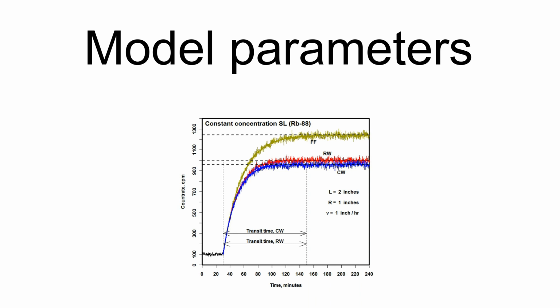Line loss refers to the losses of particulate matter in transit from a sampling point to the monitor, thus the concentration measured would be somewhat lower than that in the original sampled air. This factor is meant to compensate for these losses. Sampling lines are specifically designed to minimize these losses, for example, by making bends gradual as opposed to right-angled. These lines, pipes, are needed since in many applications the CPAM cannot be physically located directly in the sampled air volume, such as a nuclear power plant's main stack, or the ventilation air intake for the plant control room.